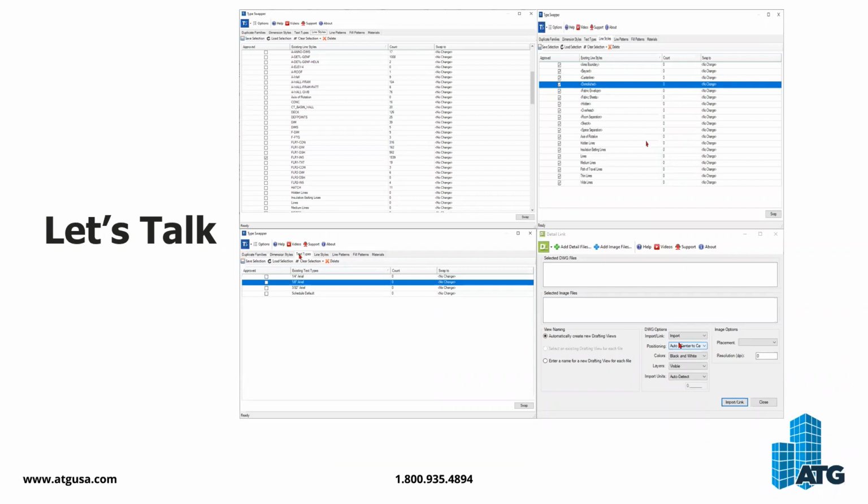What you don't want to do is go into your Revit project, an actual design project, and bring in or link in an AutoCAD detail. Well, it's not linked, import it, because that's how you're going to explode it. And then someone goes in and explodes that detail. What happens when you have an exploded detail?